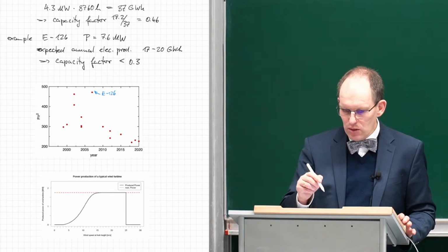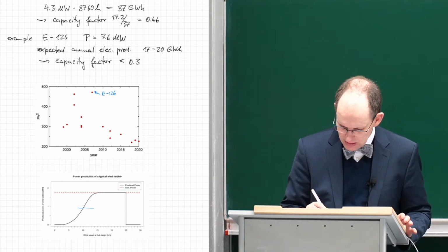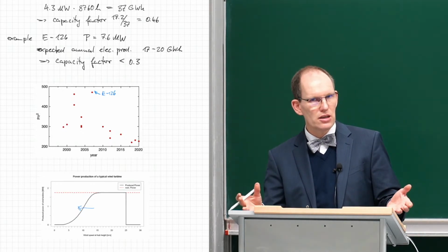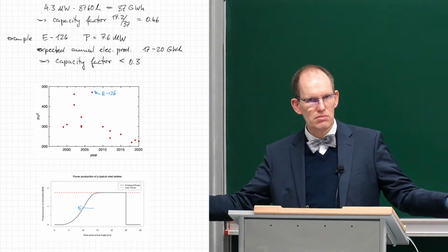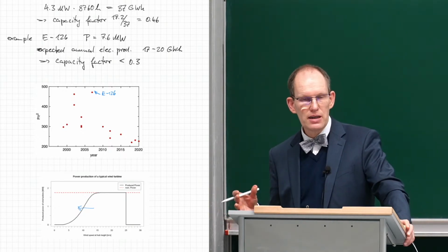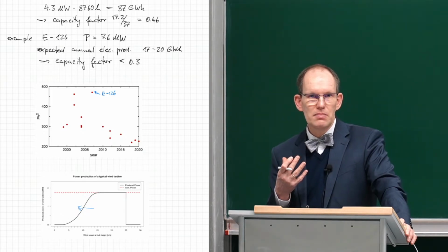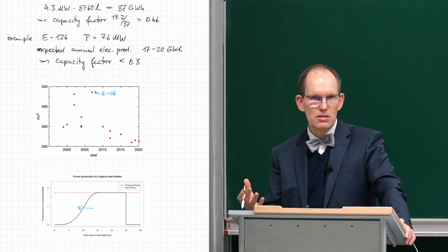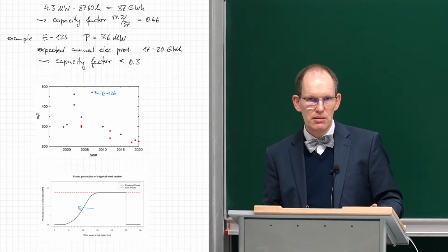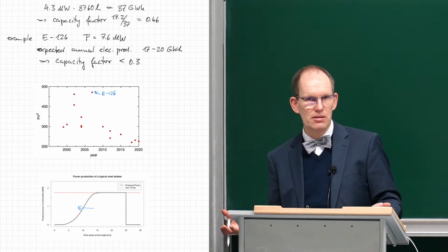Okay, now what people do is of course that they move this curve in this direction, just by installing a smaller generator on a larger diameter. And this increases the capacity factor, and of course this makes a lot of sense because what you want from an electricity generator is that it reliably generates electricity, which means that it has a high capacity factor.